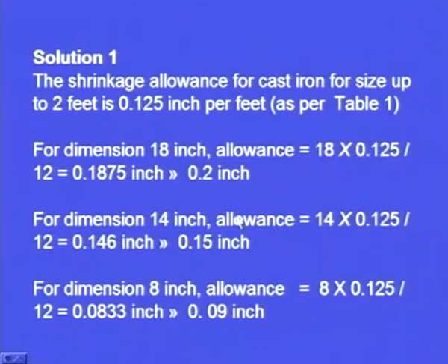And there is another side whose length is 14 inches, and its allowance is given by 14 into 0.125 by 12, that comes to be 0.146 inches. We can round it to 0.15 inch. And there is another dimension, 8 inches.